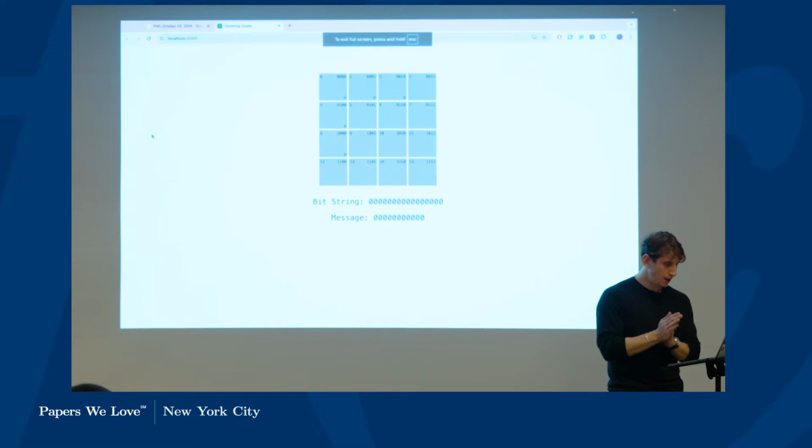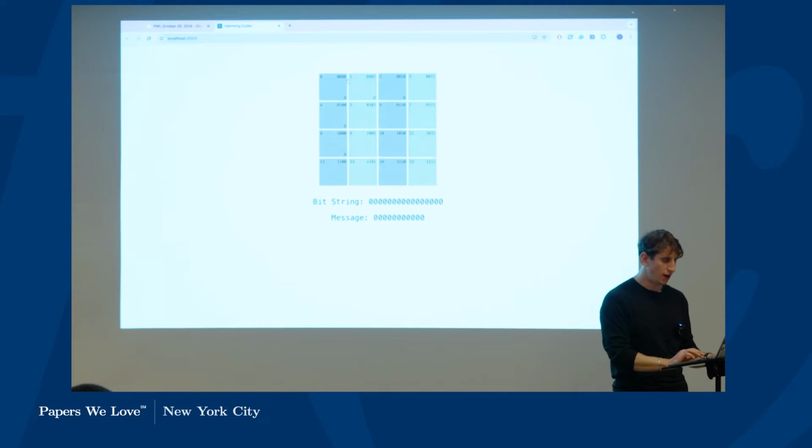So here we have 16 bits. We have the 4 check bits right here that are marked with a little P. And then you have this 0th bit right here that can check the parity of the whole message. What he gives us is a way we might construct this message. So, for example, if we take 5 right here, we need to make sure it has even parity with this parity check, and with this parity check. Finally, the whole message needs to have even parity.